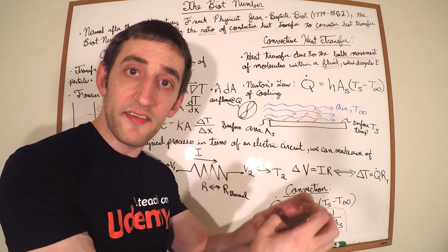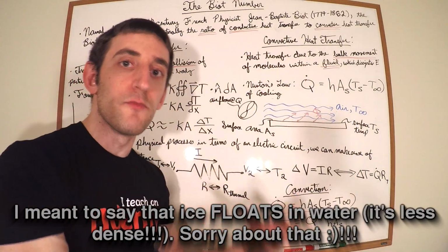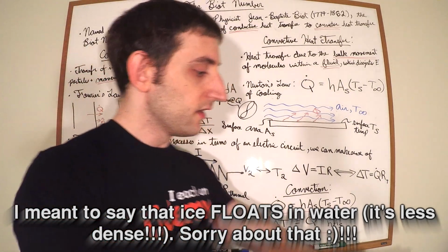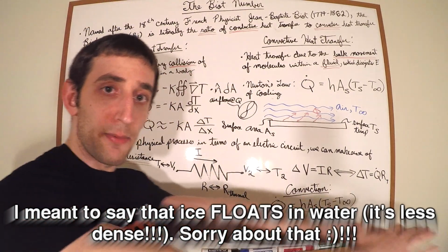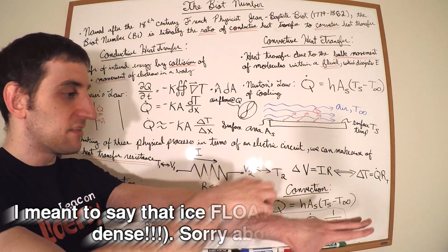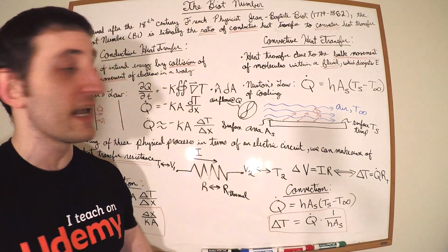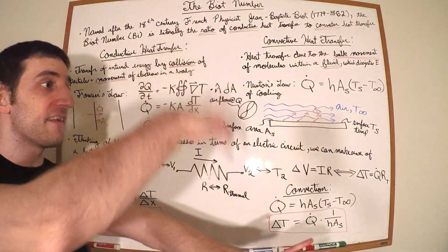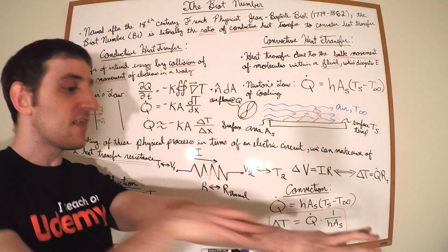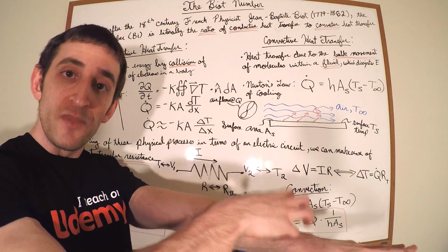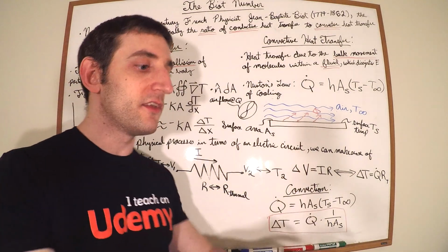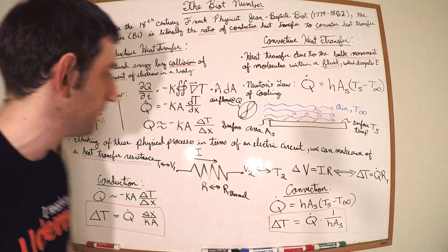That's why ice in water tends to sink to the bottom. It's more dense. So the hotter something is, the lower the density is. So that low dense air on top of the surface of the plate, it's going to rise. That's going to create fluid flow, bulk movement of the particles, and that's going to pull away the energy that was once inside of this plate until we reach what is known as steady state, until there is no temperature differential, right?